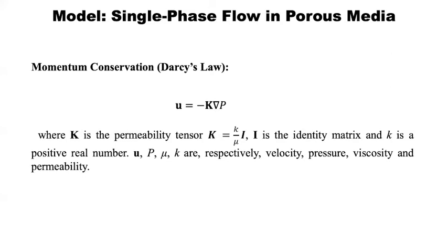So we will not be able to solve this equation unless we have another one to be coupled with it, in u and p, these two unknowns. We don't have information about velocity or pressure. They are related. Darcy's law is telling us that velocity is related to pressure, but we will not be able to know them unless we have another equation.